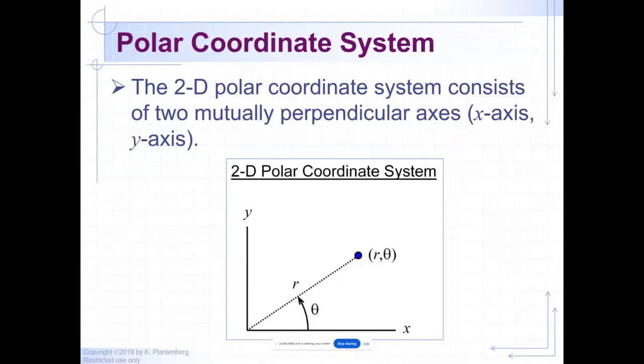But since most things are relative, coordinate-wise, in AutoCAD, they just made that the default, where if you turn on dynamic, everything's relative. The only problem is when you want to do a polar coordinate, how does it know you want to do a distance and an angle? AutoCAD doesn't. So you have to use the @ symbol, which is Shift-2. Then you put in a distance, then you press Shift to get your angle symbol, and then you put in the angle.